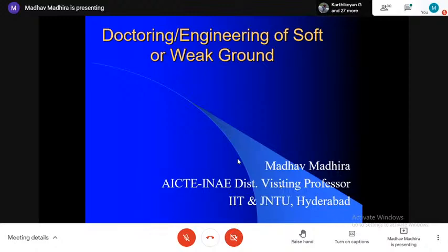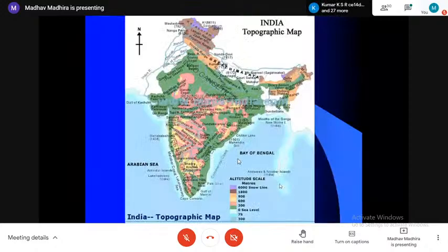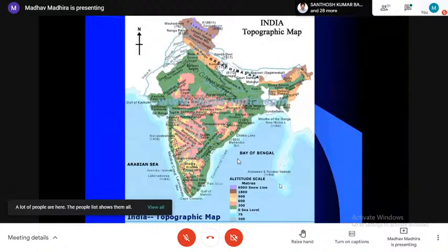Topographic map of India. I think you probably know the kind of regions. We have a long coastline. The pink area is the expansive soil in the Deccan Peninsula. The green one you can see is the Indo-Gangetic alluvium. Then you have the Sivaliks and Himalayas, which will give you a lot of boulder deposits. The green part on the left is the Thar Desert, which is in Rajasthan, and then you do get some hilly areas down south too.